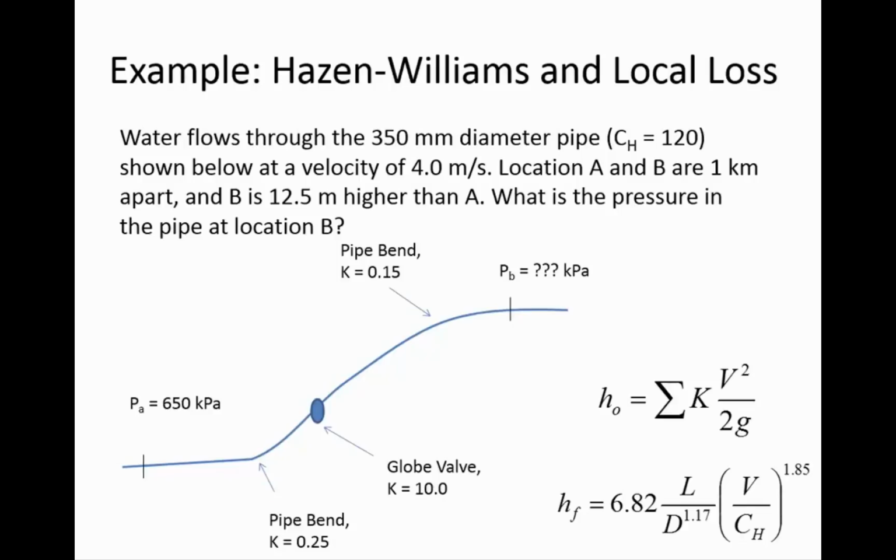And so when you have laminar conditions, then you're supposed to use an alpha of 2.0, but when you have turbulent conditions, you're supposed to use alpha is 1.05, because average velocity is a better estimate of the velocity at most locations in the pipe when conditions are turbulent.